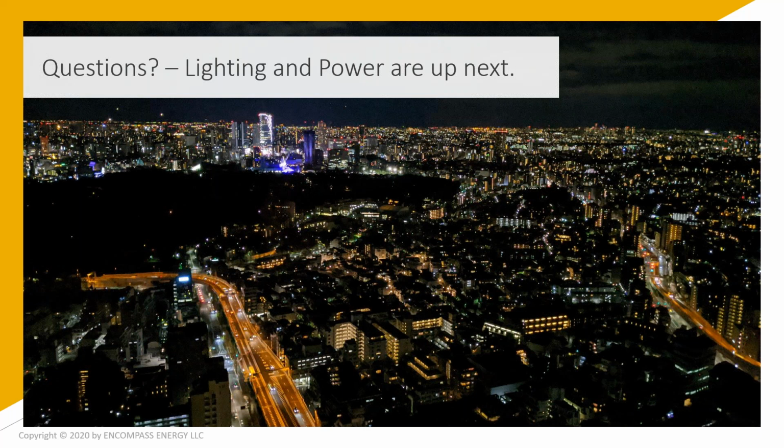There's been a lot of modeling done to prove out that there's really no difference in the energy consumption if you model all the individual zones within a dwelling unit versus one large zone. Again, it is specific to a project. If a dwelling unit is facing 2 separate orientations within a building, say south and west facing, you might need 2 zones.